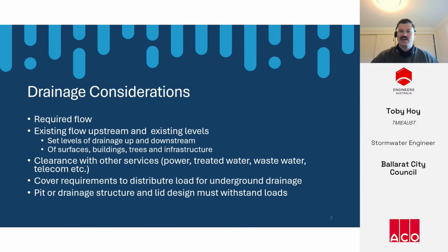Drainage considerations. Any drainage we design with existing infrastructure will need to work with existing flows and levels. We often have set levels both up and downstream that we must consider and match into. We normally have an upstream catchment we need to account for in our design. Regardless of upstream requirements, our drainage is going to have a required flow, and this is what's going to lead us to our size selection of our drainage infrastructure. Greenfield sites being the exception, we almost always have existing surfaces, buildings, and other infrastructure that we need to design around.